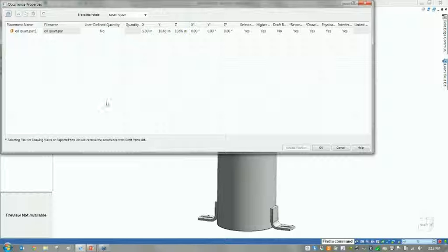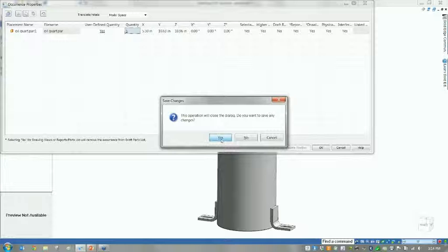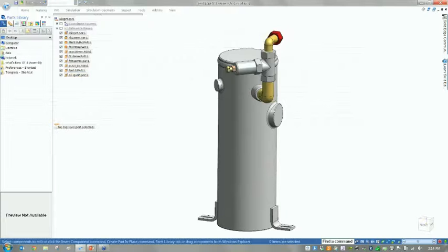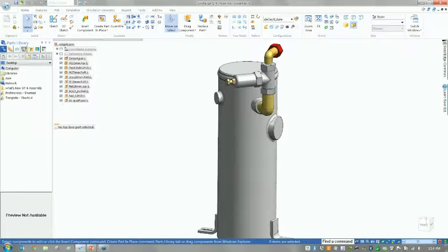This occurrence property of the quart of oil, I'm just going to say user-defined quantity. Okay, and back here it says, do you want to define the quantity of this? No, I'm going to let Solid Edge do that. I put 1 in, the bill of materials shows 1. If I click on the space and say yes, then it'll say, how many did you want to put in there? So let's say 5 quarts. It's like my car. We're going to put 5 quarts of oil in there.